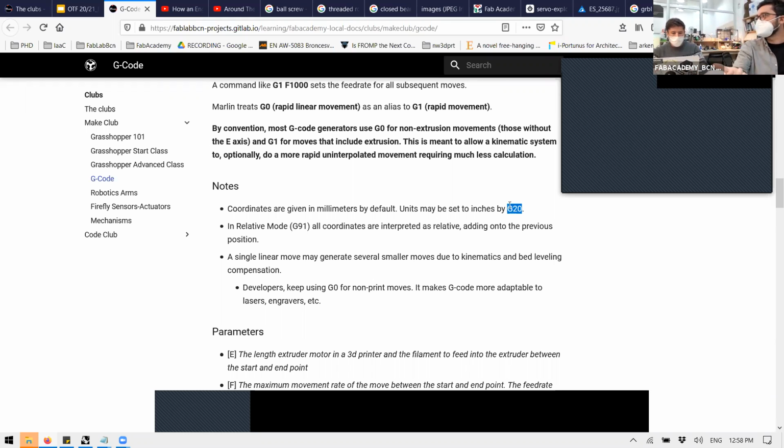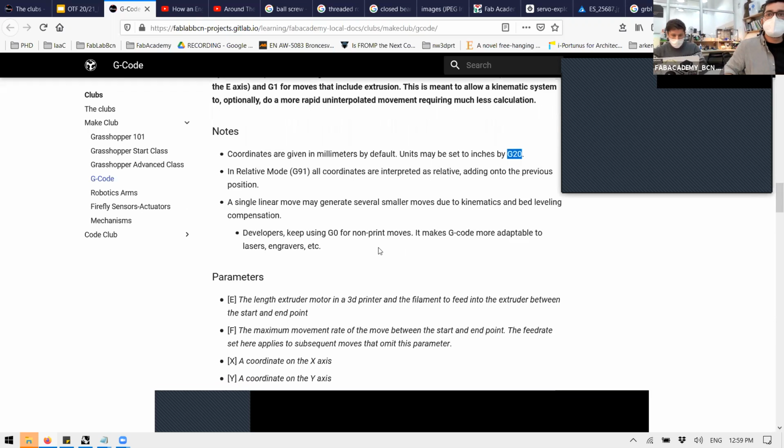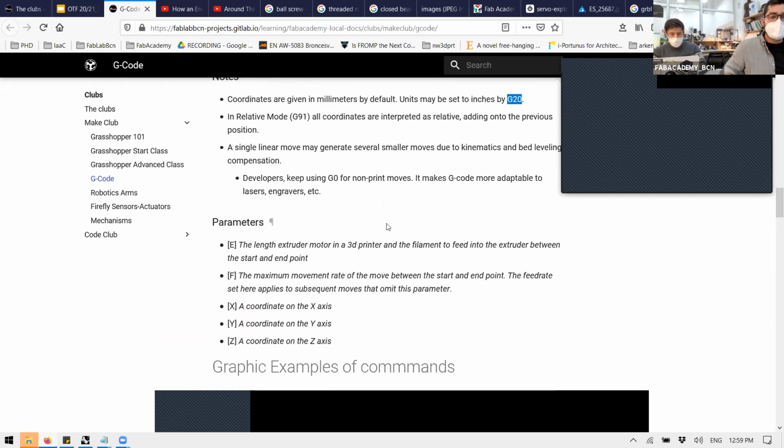We remember some G-codes, but we don't remember all of them. For example, I remember the most standard ones, M106 and M107, fan on, fan off. I don't remember, for example, how to set the temperature of the extruder. I think it's 104, but I'm not sure. We don't need to know this by heart. You can just look it up.